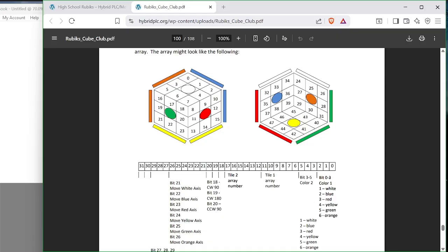And I basically built a matrix of which valves had to turn on for a specific transfer. All right? And then there were 50 some odd transfer paths. And I built up 56 of these matrices, okay? And you call up which one you wanted, and it would come in and do its thing. The other way of doing it would have been to code if-then-else logic across to do that. And I thought I would be better off if I coded it as recipes.